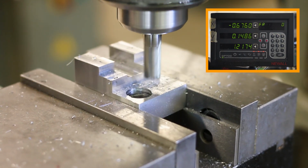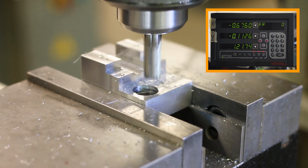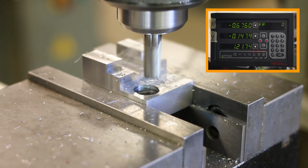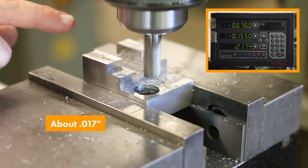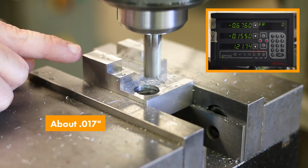Okay, now I'm going to go to the other side of the slot in the minus direction here on the digital readout and take a cut at 155 on this side, equidistant from the center of the part according to our digital readout. And actually, you know, it looks like this side was significantly larger than this side, so I guess the roughing end mill didn't cut perfectly on center.